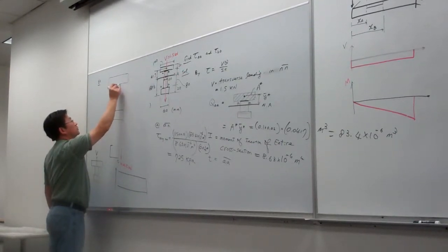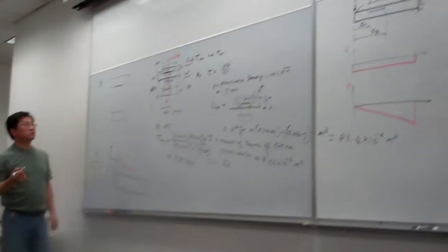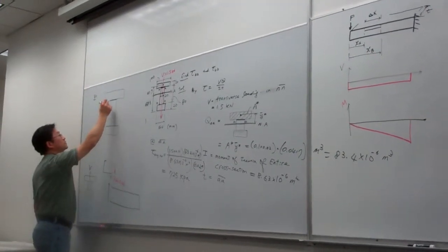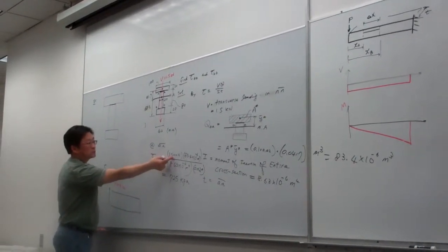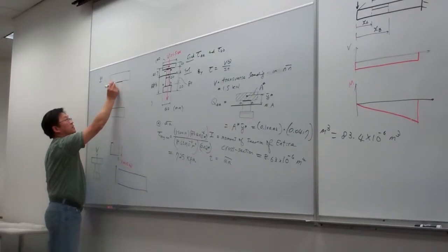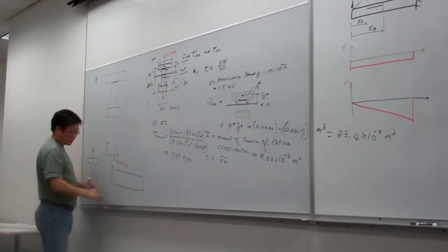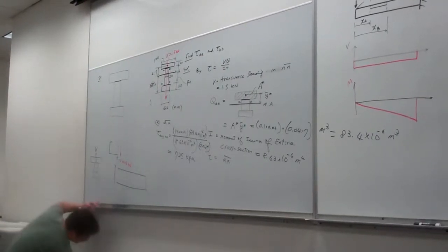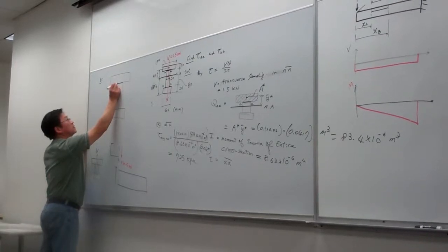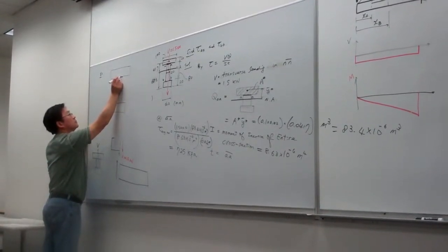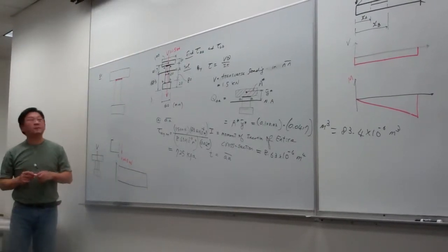So along this edge, AA, locally the shear stress is like this. The shear stress is induced by transverse loading. So on this side, the transverse loading is working downward. So the average shear stress will be the same thing here. Along this edge, that will be downward. Okay.